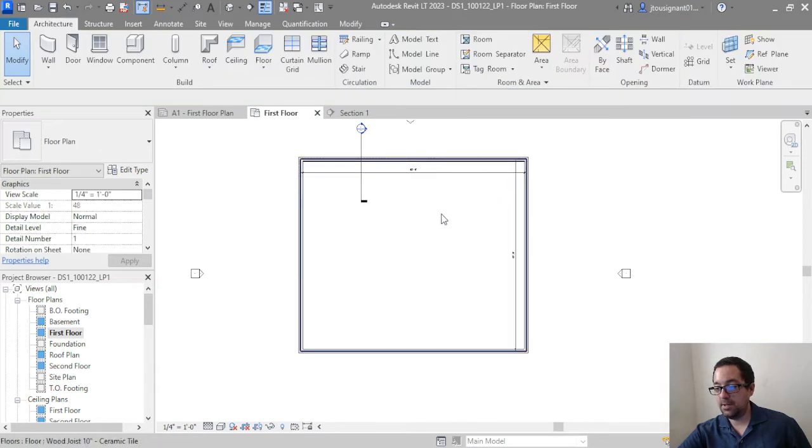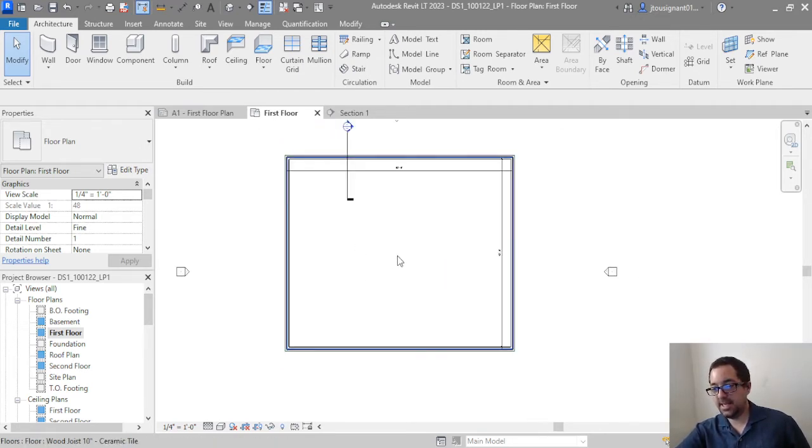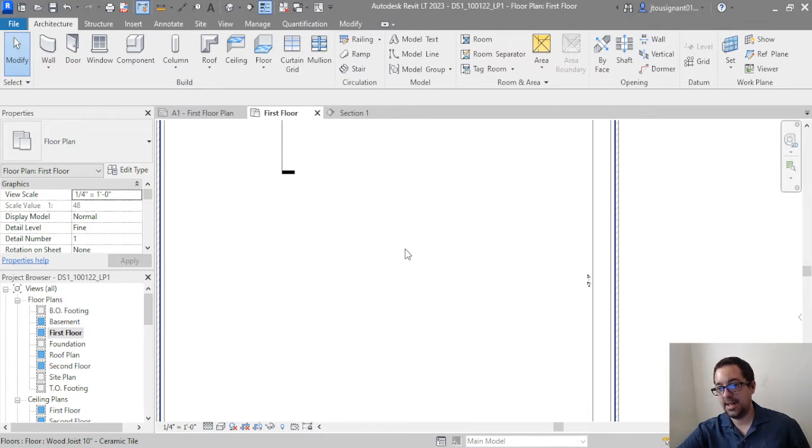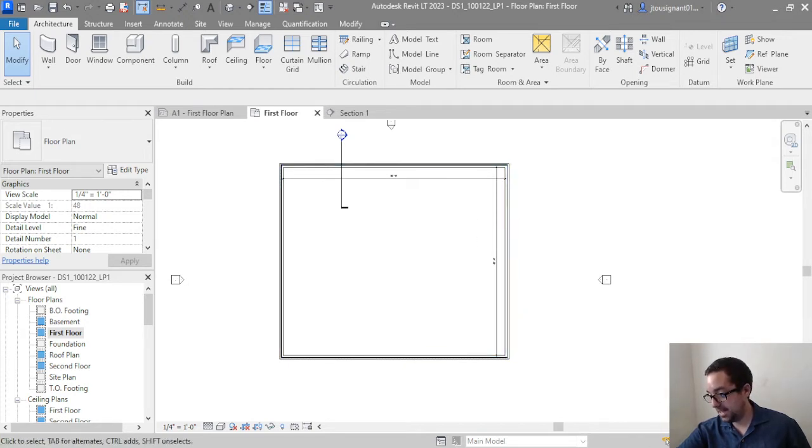I wanted to point out, many people have problems with clicking on one of the items inside of Revit because, like this floor, you don't necessarily see the floor. You are looking in a space that contains the floor, but it doesn't have a hatch or anything like that. So when you click, sometimes you don't get it. I've always got my Revit set down here in the bottom right corner, right beside where the lock pin tool is and such. This is going to be a button that's helpful. It's going to let you choose surfaces, choose faces.